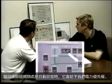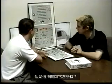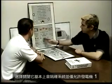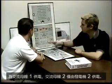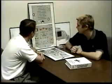The bus tie switch, when it's in auto, it's giving us our electrical priority, but what about selecting it to off? Selecting it off basically isolates the system and allows generator 1 only to power AC bus 1 and AC bus 2 to be only powered by generator 2.